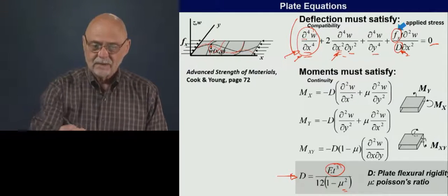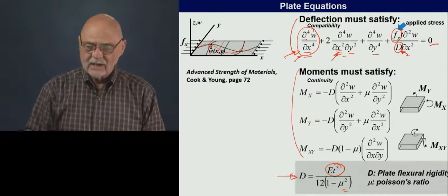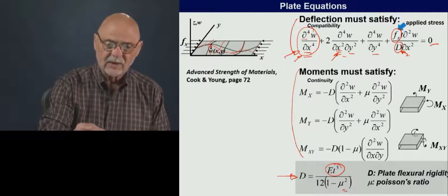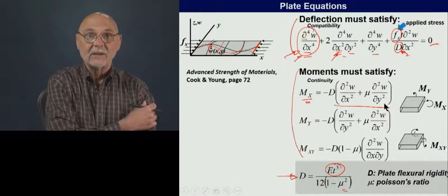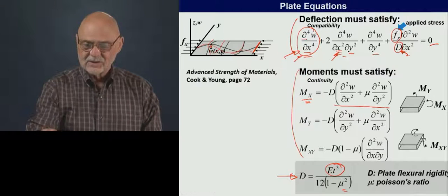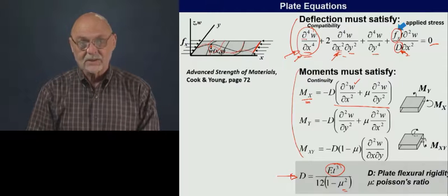There are some boundary condition constraints, so that if we look at the edges of the plate here, the moments must satisfy these relationships. And again, they look intimidating, but it's just taking some derivatives of whatever we assume for the deflected shape.